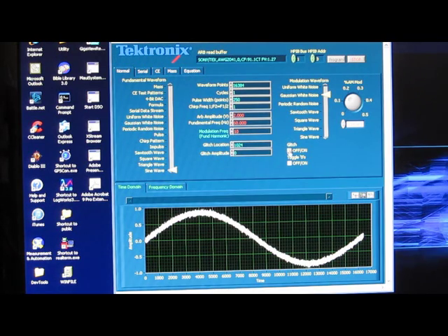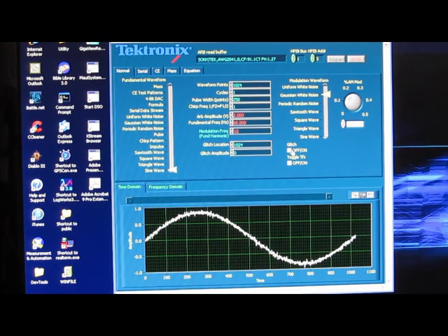There's another feature down here called glitch. Glitch will output a spike here. You can see it right now. You can change the size of the waveform or the number of data points. So I'm going to just change this to 1024 points. I can turn on a glitch, and I can tell it the location of the glitch. So for example, if I tell it at 200, it'll output at a single point.